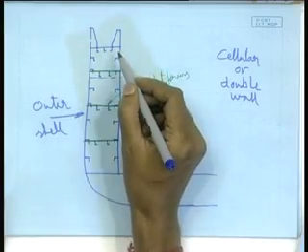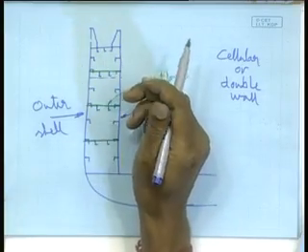Like the deck is a member which contributes towards longitudinal strength, because the deck plating is continuous all along the length, similarly, these platforms are also continuous, barring the engine room, the entire region wherever it is there.